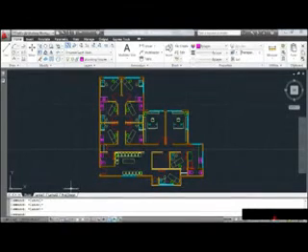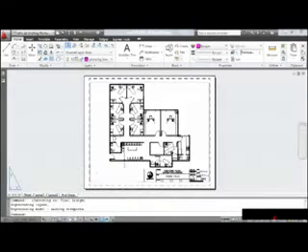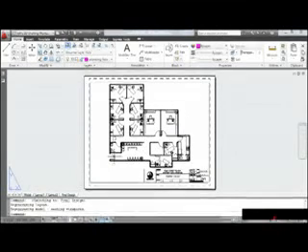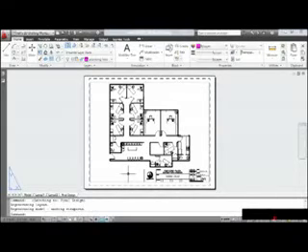Take a look at my layout tabs. Notice that I've already copied a layout into this drawing. And if I select the layout, you can see that I've set my geometry to a scale, and I've filled out the rest of the title block information. So essentially, this layout is finished. Well, except for the name. I called this sheet OV1, so I'd like to rename the Layout tab as well. To do that, I'll double-click on the tab name. I'll call this OV1, and I'll press Enter.